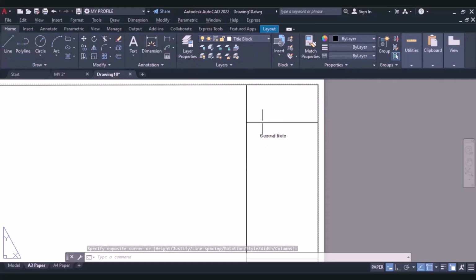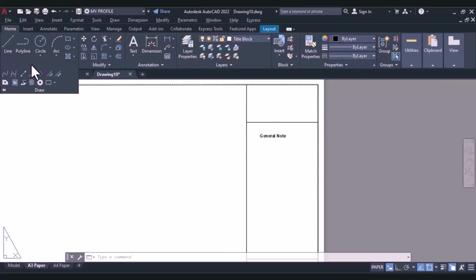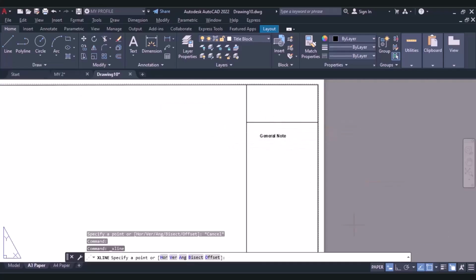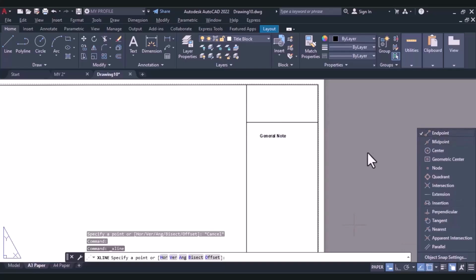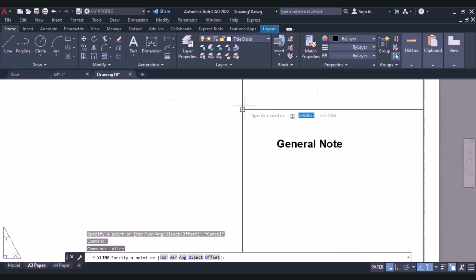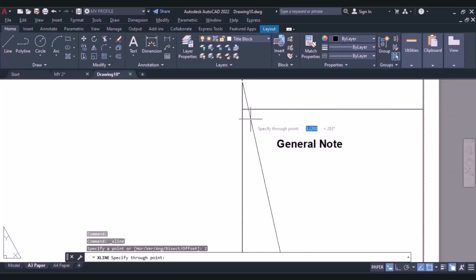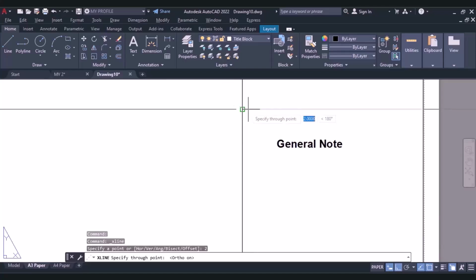Before I place my text, I will insert a construction line by clicking on the drop down, and selecting the icon over here, which is the construction line. I will select it. I will go over to my snap to object, click just the end point. I will click out. This time I will select this point, click it towards the right as 2 millimeters. Okay, and I will turn on my auto mode. Okay, this time I will place it here.